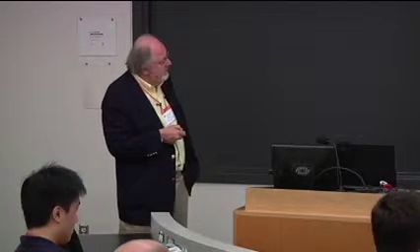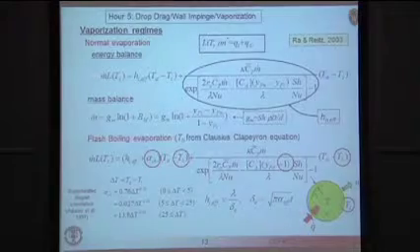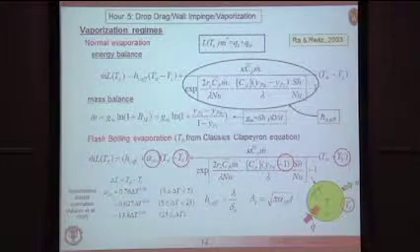So the other thing that you'll notice here, this circle is an augmentation to the effective heat transfer coefficient for the heat transfer process inside the drop. And this is due to nucleation phenomena that can occur when you have flash boiling. So basically, you're stirring up what's going on inside the droplet because of bubbles. We spoke a little bit about that earlier.